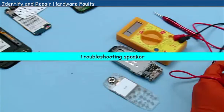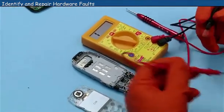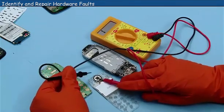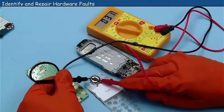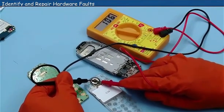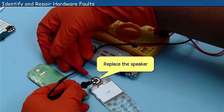Troubleshooting speaker. In a mobile speaker, there is no positive or negative terminal. It works when it is connected to the IC. To check the speaker, take a multimeter and set it in ohms range. Connect the probe to the 2 pins of the speaker. If it shows a reading and there is a beep sound, then the speaker is in good condition. If we interchange the probe, it has to show the same reading. Otherwise, replace the speaker with a new one.